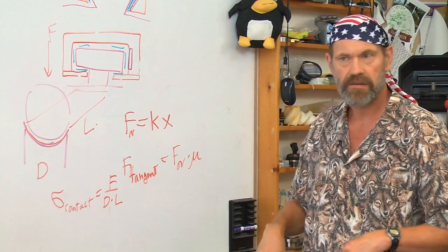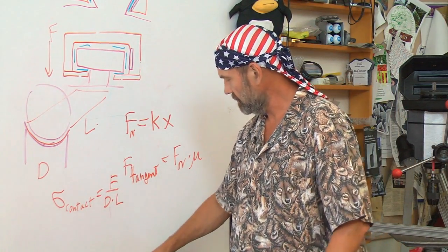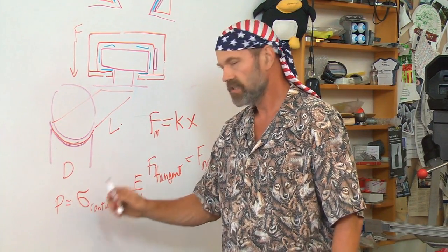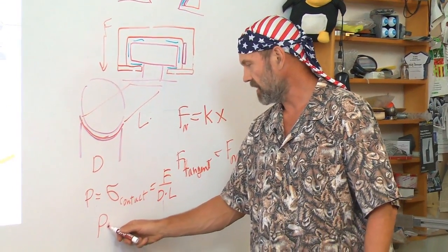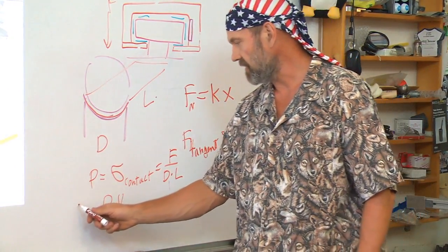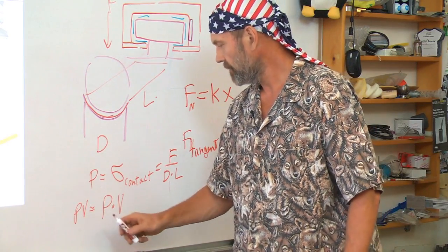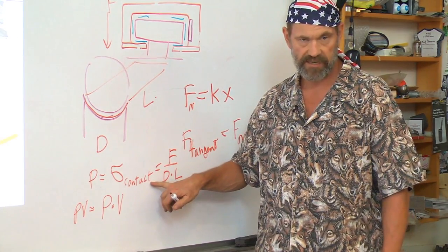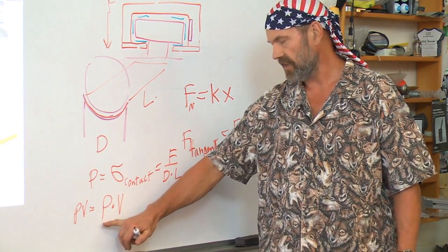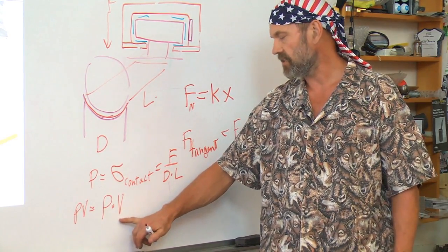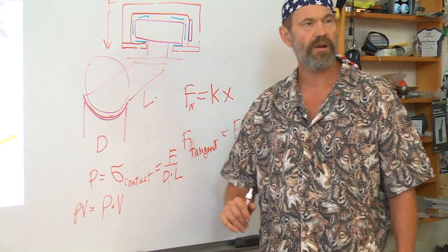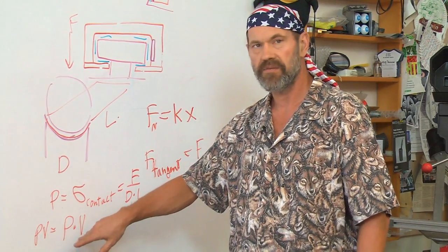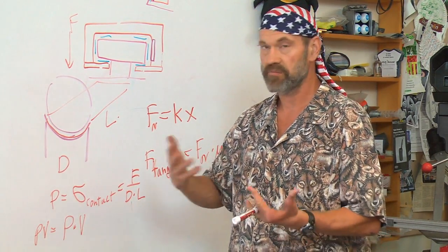Starts hot. Worrying about what is called sigma, or pressure. Sliding contact bearings have a pressure times velocity limit. This is called the PV value. So you'll have to stay below a threshold, or maximum contact stress, and the contact stress you do apply times the velocity you apply will govern the wear of the bearing. That's all covered by the manufacturers in terms of what wear can be expected at different PV values, and what's the maximum PV value before you just burn up the bearing and melt it.